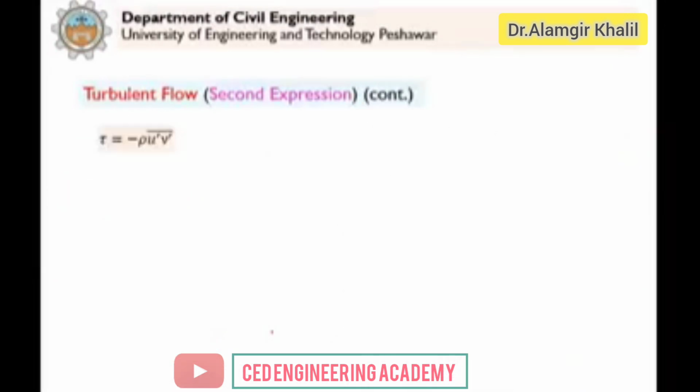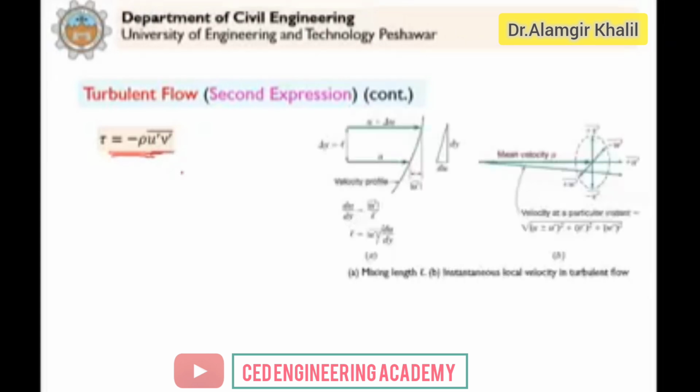Now if we proceed, this is the expression that we get, clear? And this is known as the Reynolds stress, because you get the stress units. Shear stress is given by this quantity, clear? But then the problem is that we have to measure these products of fluctuations for a long period of time. So it is very difficult to measure this quantity. So what we have to do is express this shear stress in the form of an equation that we can measure.